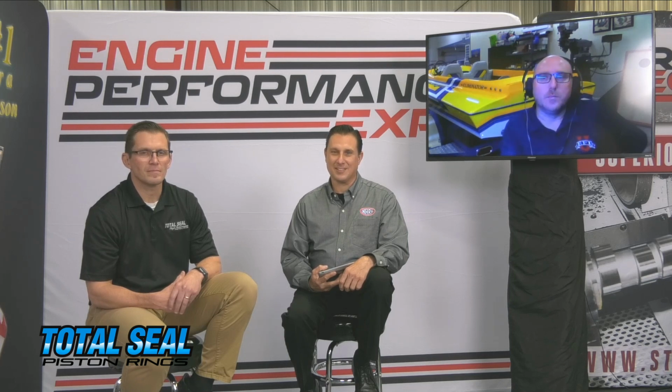Ours is a little bit different than most of the ones out there, but it was the keys to the kingdom, really. The idea of running an engine 8, 9, 10, 11,000 RPM on the dyno was totally terrifying before the Spintron, at least in our shop, before we did the Spinal Tap project. And for us, the combination of understanding why we needed to look at that stuff with the Spintron and understanding a little bit more about the low shock concept has changed everything. I don't know that we even do hardly anything anymore that's not low shock, to be honest with you.